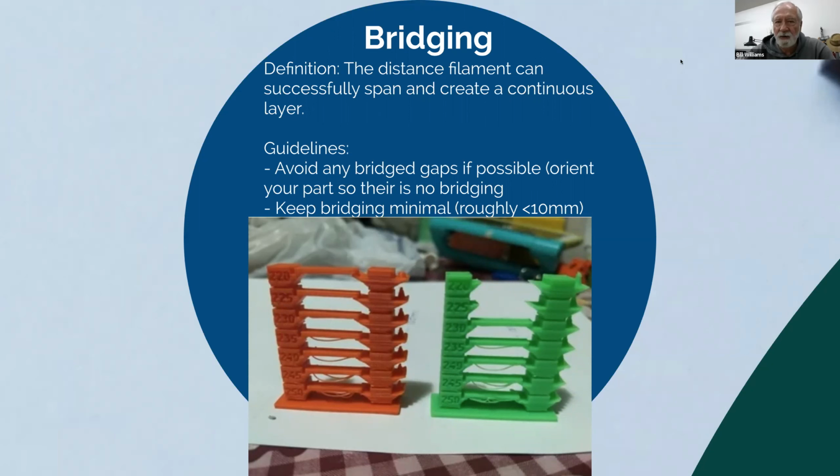You mentioned a chamfer on the bottom of a part. How do you get rid of that on the part later? I mean, you have to grind it off or what? If the chamfer doesn't work within the function of your part, then yeah, you would have to build that in and then remove it later. Okay.